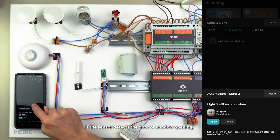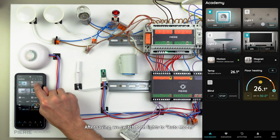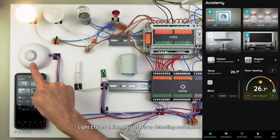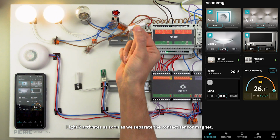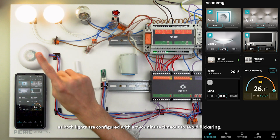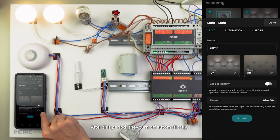If the sensor detects the door or window opening, the light will turn on. After saving, we switch both lights to auto mode. Light 1 turns on immediately upon detecting movement. Light 2 activates as soon as we separate the contact sensor magnet. Returning the magnet doesn't switch it off immediately, as both lights are configured with a 2-minute timeout to avoid flickering. After this period, they turn off automatically.